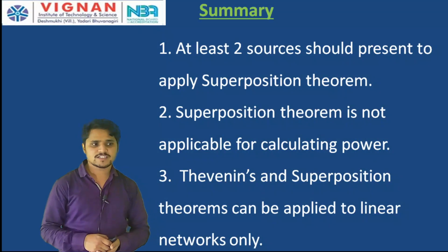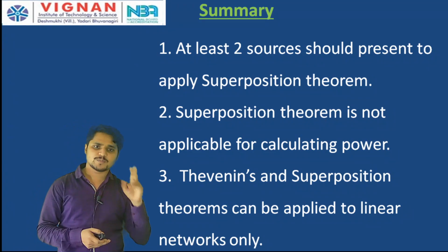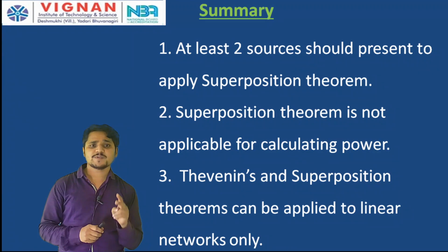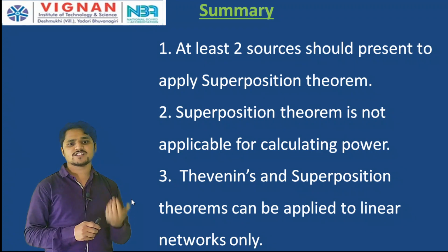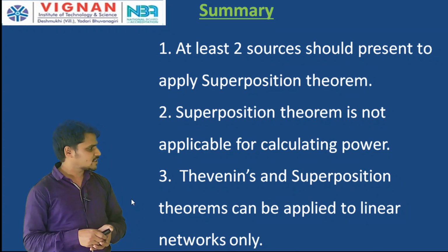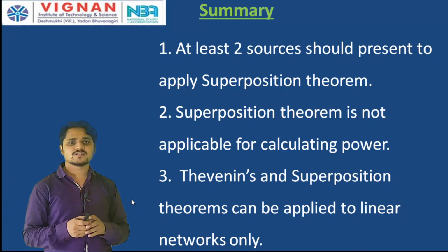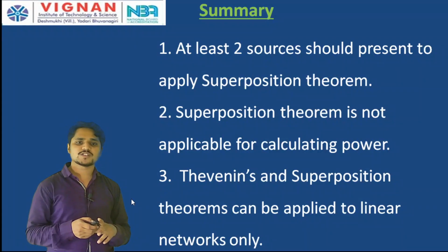Let us summarize today's lecture. To apply the superposition principle, at least 2 independent sources must be present. Superposition theorem is not applicable for calculating power. Thevenin's theorem and superposition theorem can be applied only to linear networks; the limitation is that they are not applicable to non-linear networks. This is the summary of today's lecture.